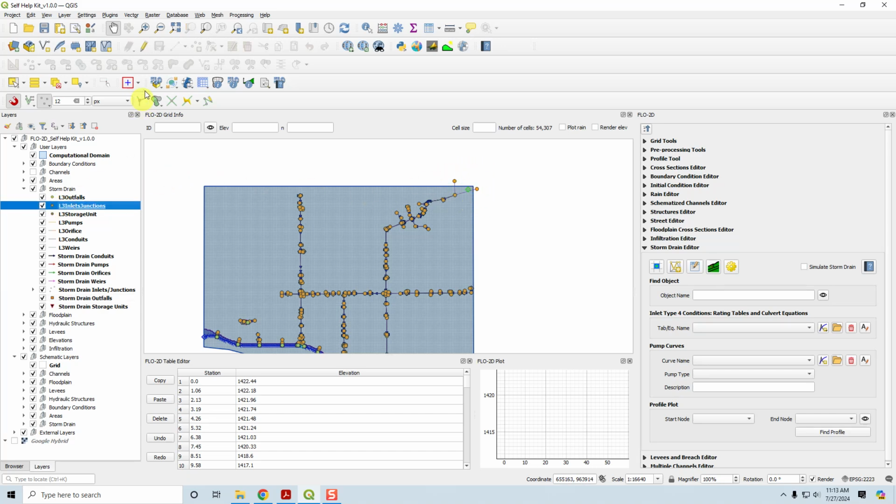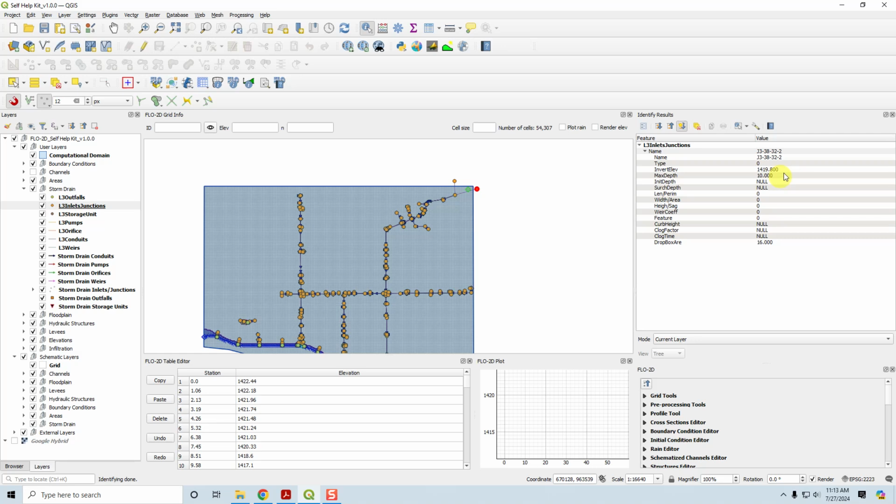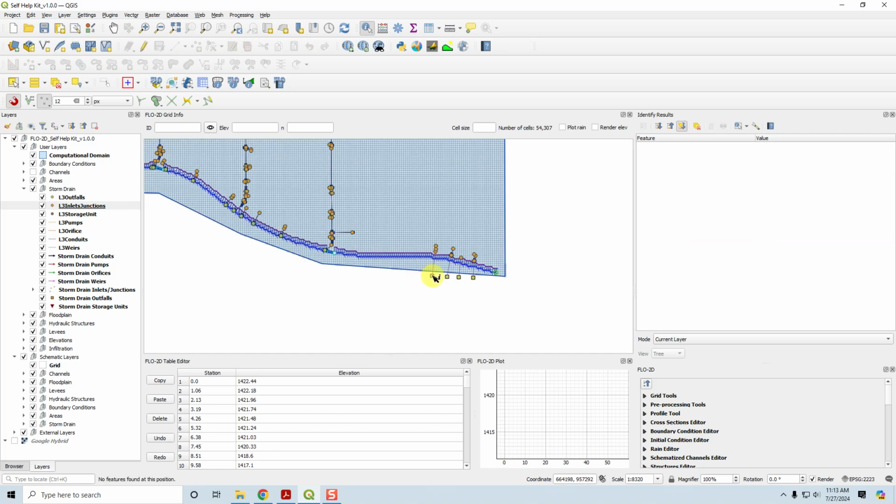Okay, let's identify these features. You can have a feature that's off-site so long as it does not try to connect to a grid element. So the feature has a name J, that means it's not going to connect to an inlet. And then down here I have some outfalls, with the name O, which is an outfall, is fine, but their allow queue type is 0, meaning that any flow that flows through these will just act like a sink. It'll just flow off the system at a free discharge. Okay, so that's what those do. So they can be off-site.